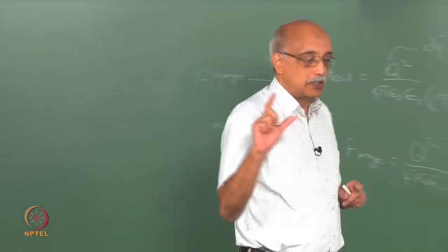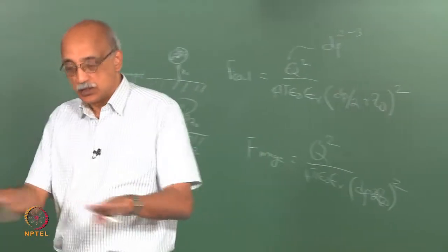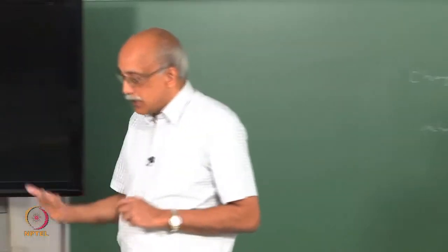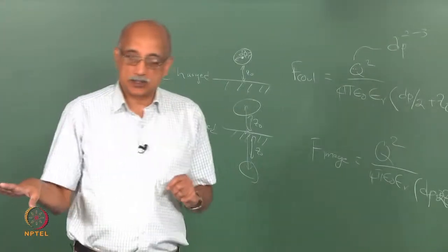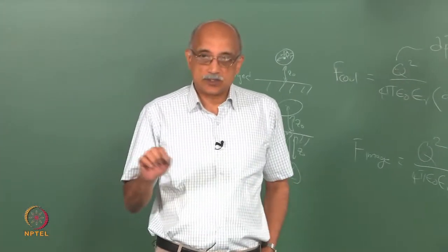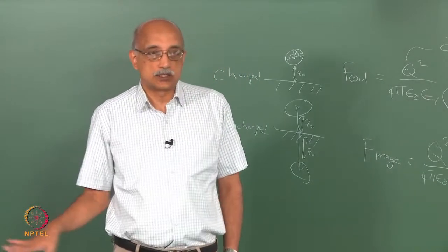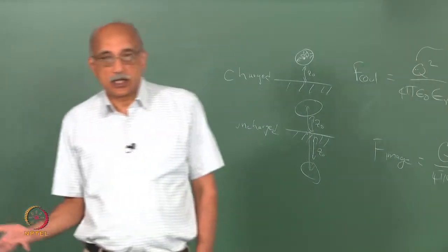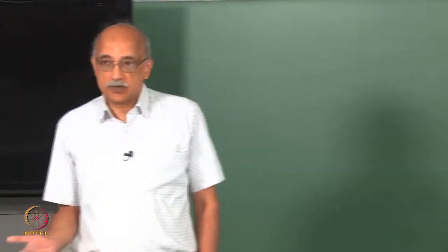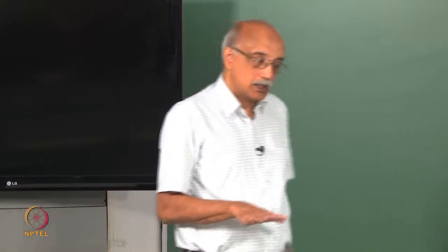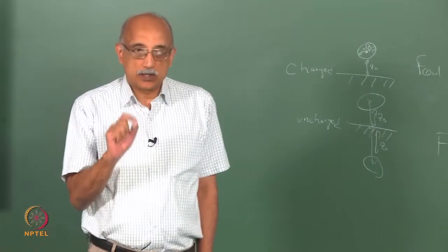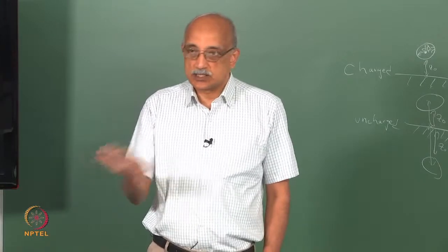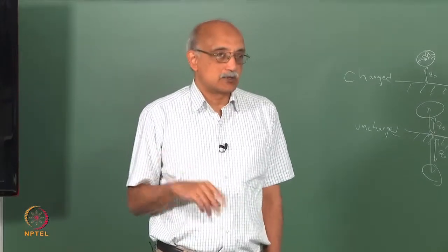I mentioned that high affinity of the particle to the surface is good because it gives you a closer polish, but there can be a downside to that as well. One of the difficulties when you do this CMP process is that the slurry particles can themselves get embedded on the surface that you are trying to polish, in which case they become a contaminant that can actually have an adverse effect on the functionality of the device that you are trying to make. So, again, ideally you want a slurry which does extremely fine polishing, but the particles do not stick on the surface, that as soon as the polishing is done the particles are removed, and that is sometimes difficult to accomplish.